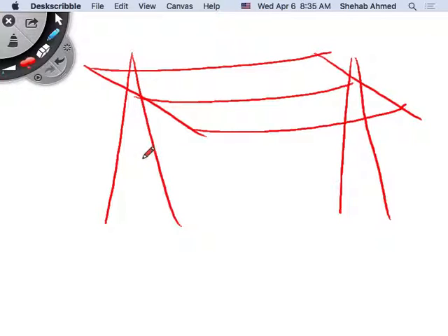So the tower is grounded. So if something like that happened, it means that actually one of the transmission cables fell and hit the tower, for example, right? Or swayed enough so that the insulator broke and hit the tower, right? So it may happen, but of course I think the probability is very low there. The probability of it happening when people are doing a construction project or a building project, or in your home, that's very common, right? It's very, very common to happen. So it's the most common type of power system fault, yeah.